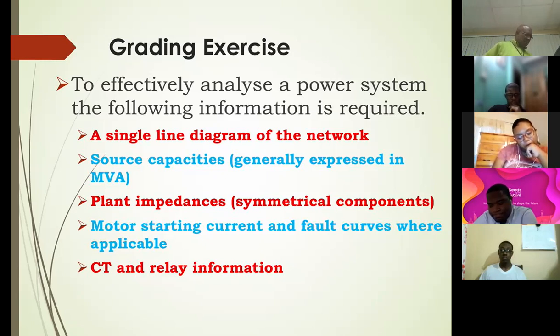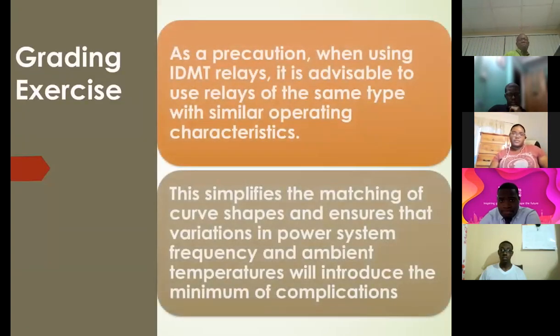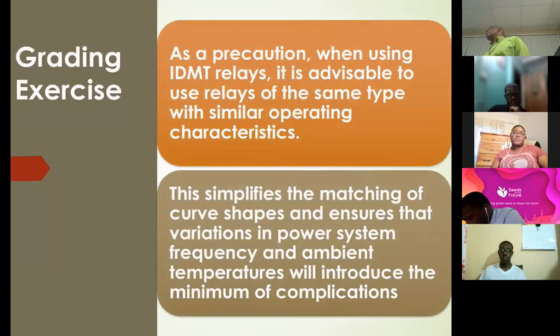And just a note, one, when you're using these relays, you want to use relays having the same characteristics. So you're not going to mix IDMT and not IDMT, very inverse and extremely inverse. It's not that it cannot be used.